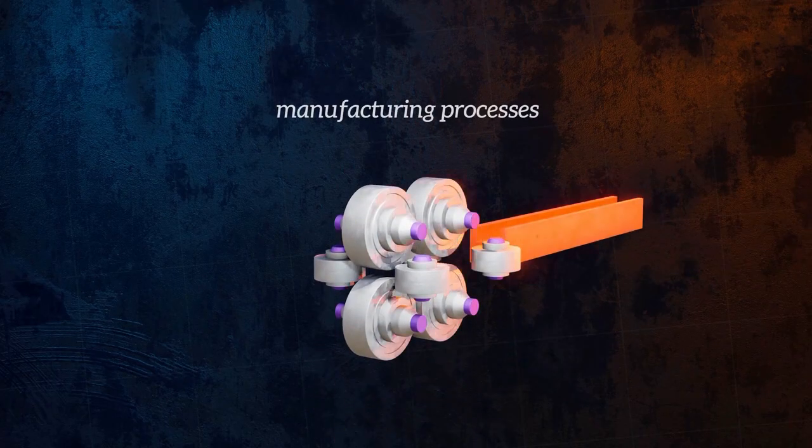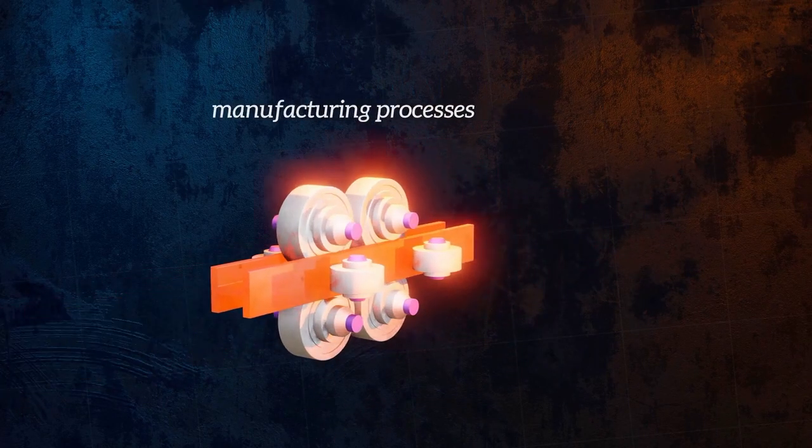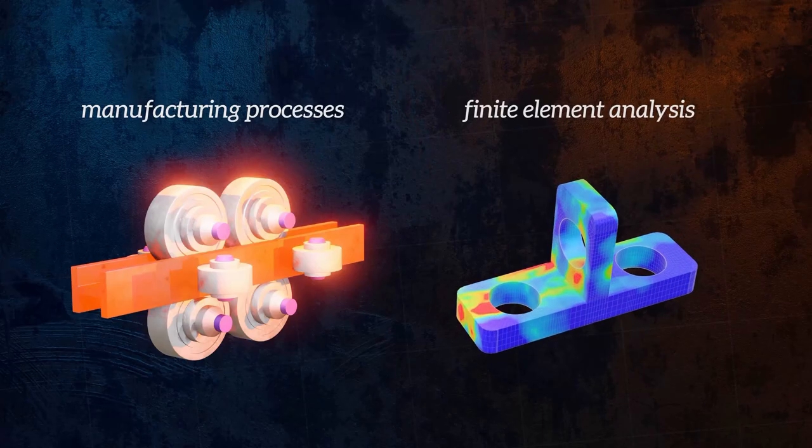Examples of this might be the analysis of manufacturing processes, or performing finite element analysis, which models large strains. By making a few assumptions, we can calculate the true stress-strain curve based on the engineering curve, and so we can avoid having to measure the instantaneous cross-sectional area during the tensile test.